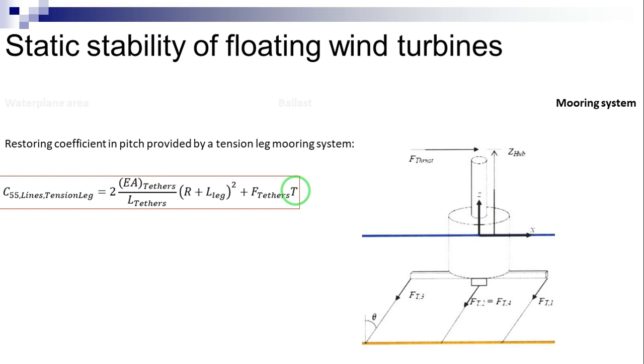Therefore, considering infinite stiffness prevents any significant motion in pitch, roll, and heave, which are the motions in the vertical plane, but the mooring system must limit the motions to reasonable values in surge, sway, and yaw, which are the motions in the horizontal plane.